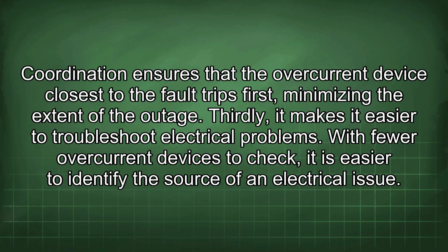Coordination ensures that the overcurrent device closest to the fault trips first, minimizing the extent of the outage. Thirdly, it makes it easier to troubleshoot electrical problems. With fewer overcurrent devices to check, it is easier to identify the source of an electrical issue.